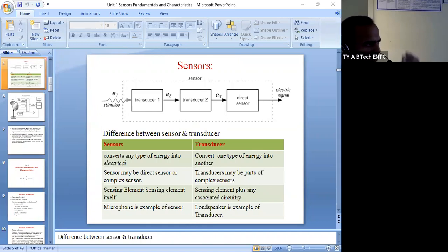That is the selection of multiple inputs. Suppose 4 inputs are there, 8 inputs are there, 16 inputs are there. Out of that, you have to choose only one output at a time. So if your combination like ABC or ABCD is such that the 7th input is selected, only the 7th input side output is transferred towards the output. If you change the selection combination, either 3-digit or 4-digit or 2-digit, whatever the requirement is, you will get the next output.